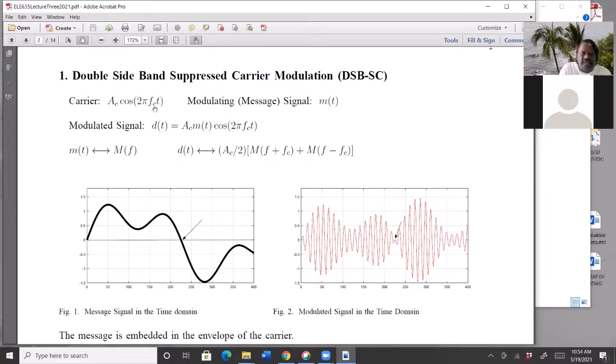The carrier signal for 680 News is 680 kilohertz. The total AM band in the radio, you can see it in the car radio, is about 450 kilohertz to 1500 kilohertz, so 680 is kind of in the middle. Always keep that in mind. This fc is much higher than the highest frequency in the message signal.